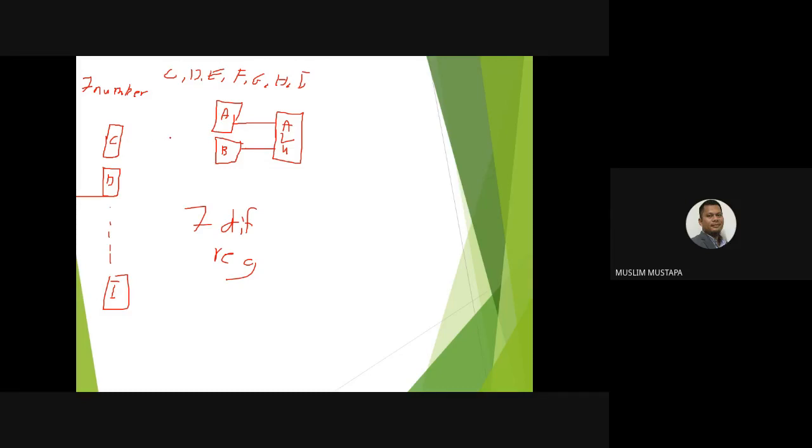So how are you going to do that, right? So that you can select it easier. Which one are you going to fit into A, which one are you going to fit into B, right? So that's why in this case, we need to use muxes, right? So we have muxes. All of this input is going to be connected to both muxes, and then it's going to go into A and B.